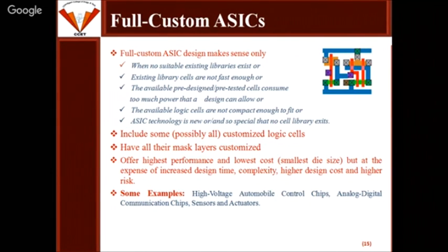Fine. So in that we are basically defining each and everything. We are defining the MOSFET, we are defining the device, as well as the interconnections. You can think of this as the basic difference between full custom design, where we are defining each and every part of the circuit and every parameter, while in semi-custom design, we are just assuming that the library has the components, and we take those components, interconnect them and form the device.